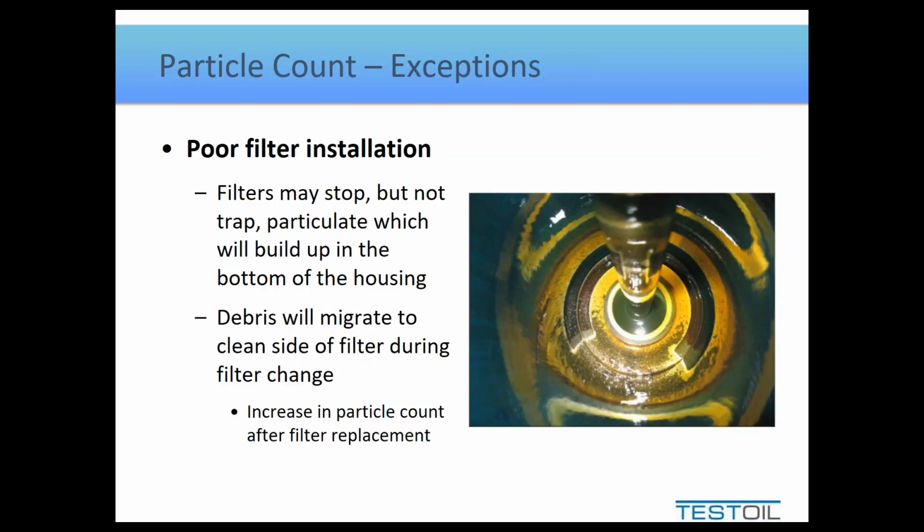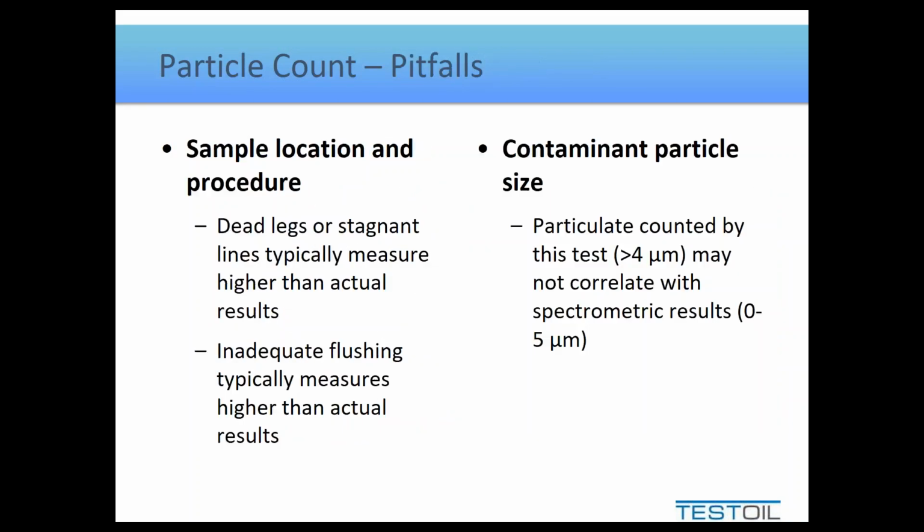Now, the pitfall with interpreting particle counts is that we have to appreciate that where we take the sample also has a significant impact on the particle count. So if we don't always sample from a consistent location, we're probably not going to get a consistent particle count.